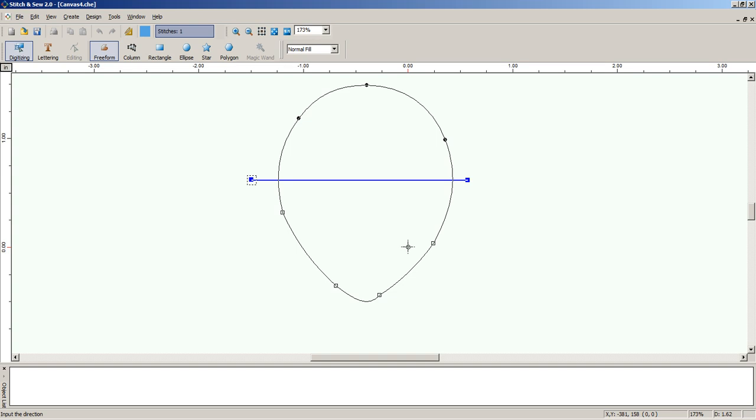If you want it to run at an angle, then just drag that second point to whatever angle you need it to be. You can make this line as short or as long as you like. It doesn't matter, as long as you draw that line to the angle that you want it to set. I'm just going to guess about a 45-degree angle here like this, and I'm going to let go, and watch what happens at the bottom left corner of the program when I let go.